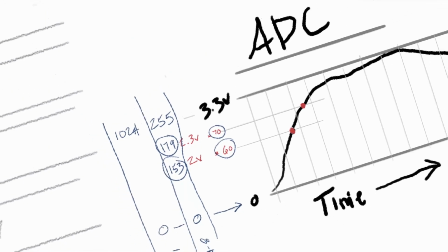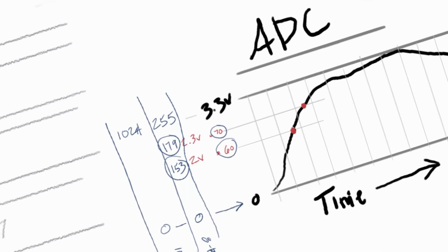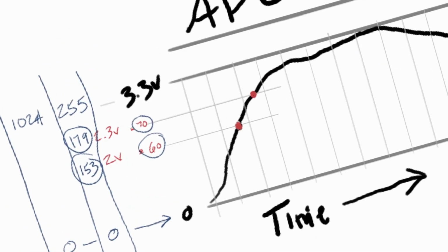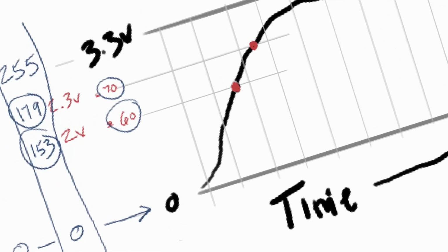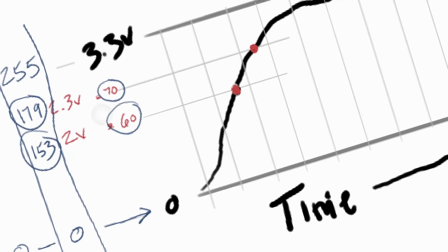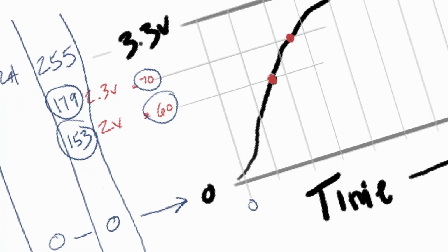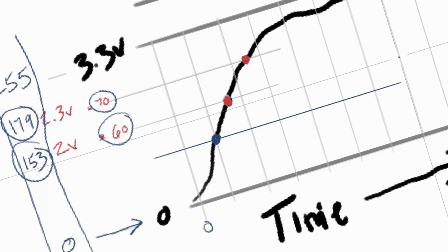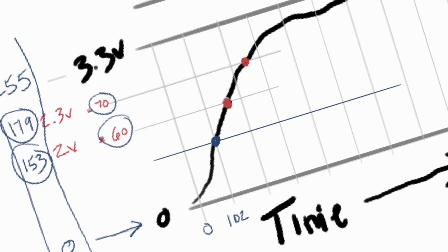You don't really need to convert it to a temperature if you're really going to use it in some other kind of computation. So you can have the microcontroller constantly reading what this temperature value is, or whatever this device is reading from the environment. And this will happen through time. When you turn your microcontroller on, you can start reading the signals from the analog device. It'll start out at 0, and then these would be like 8-bit numbers here, and then you'd have another one here. That would be around, let's say, 102 in 8-bit number.